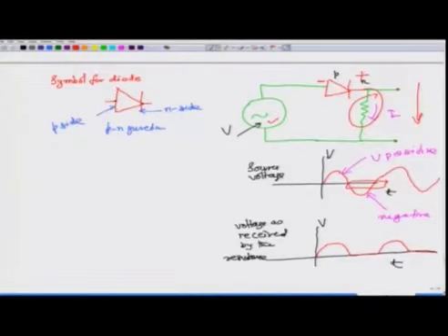So, that is how the basic unit of rectification, going from both directions to a single direction, going from changing direction of the current to the same direction of current, can be taken care of just by one PN junction put in the circuit. Now this is known as half wave rectification. Why half wave? Because half the time it is 0, it is doing nothing. Half wave rectification.